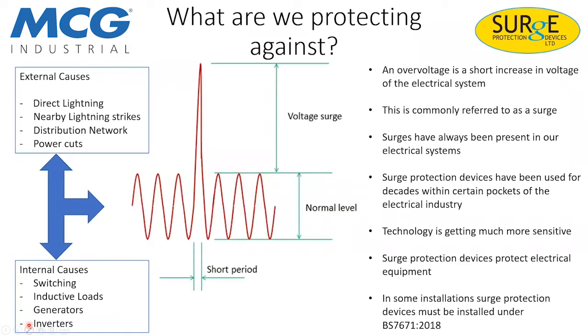So what are we protecting against with our surge protection? And I know this might sound like a bit of a silly question, especially with the name of my company. But for a lot of people, when they hear about surge protection, the first thing they think about is lightning. And lightning is a part of it, but it's a very, very small part of what we actually look at with surge protection. So an overvoltage is a short increase in voltage of the electrical system. So it's a very short, sharp spike, as shown here on this image.